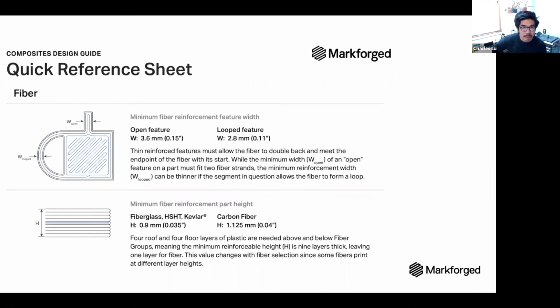You might have to put your information in again to get it, but the fiber width is about 1 millimeter, right? So each pass of the fiber is about 1 millimeter. So when you're factoring for the design of a part, imagine each fiber path is 1 millimeter, and let's say for a 10 millimeter wide part, you get about 20% for a single ring around. And you get 40% for 2 rings around, 60 for 3 rings around. So that can be used as a baseline for estimating, but unfortunately, we don't have any FEA tools yet.